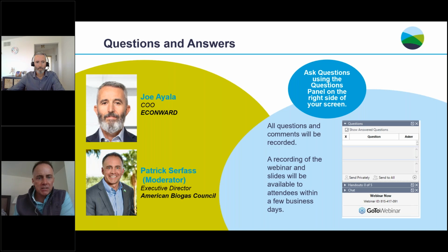I'm going to start with a couple questions that came in on your parasitic load. So there's a question on what's the energy consumption of the plant and how much water is required for these systems. Could you address that, Joe? Yeah, absolutely. So we need 1 MMBTU of natural gas worth $5, whatever, to produce 5 to 7 MMBTU of RNG injected into the pipeline. So if the RNG is worth, say, $20 or $40, you do the math, right? So we spend $5 in energy to produce 100 or 200 or $300 in energy.